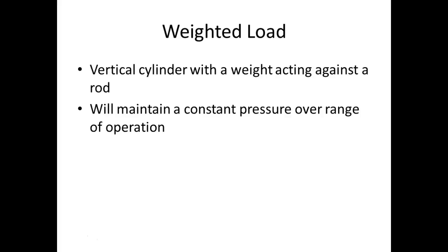Same thing. So even though the fluid over here was vibrating, when it hit that accumulator, what did the accumulator do? Well, it absorbed it. So when the pressure tried to drop off a little bit, the accumulator fed. When the pressure went back up, the accumulator would recharge. So we use accumulators to even out the flow of the hydraulic fluid. Even though you're out there jerking these things around and moving stuff, getting more flow, no flow, this guy has a tendency to maintain a constant pressure, even though we're trying to get a pressure drop in our system, right? And plus, they give us pressure even when the power fails, over a limited time. We'll maintain a constant pressure over a range of operations.